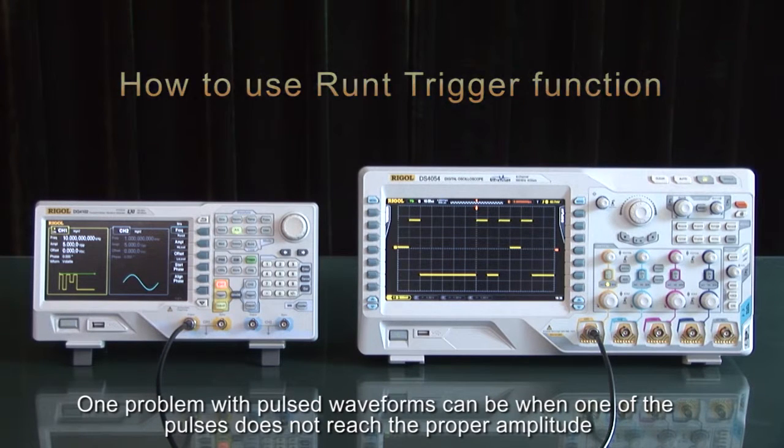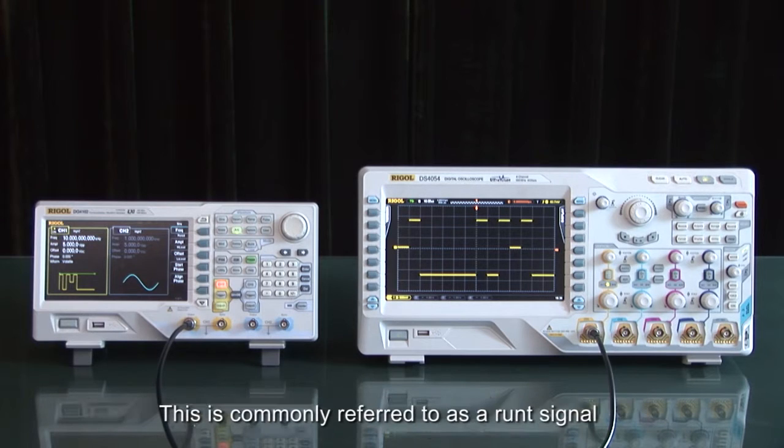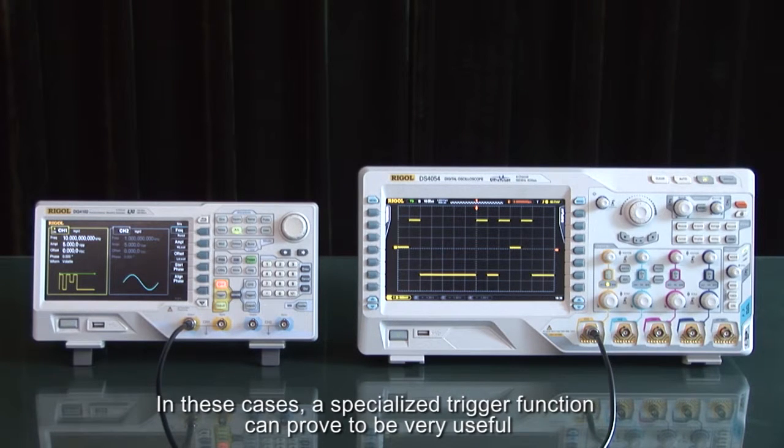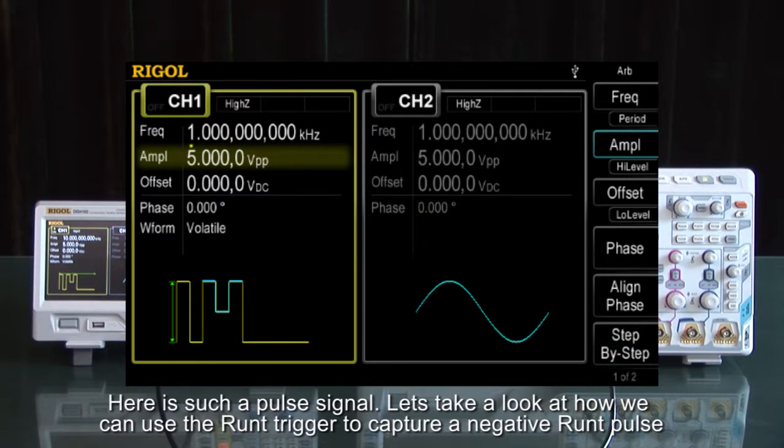One problem with pulsed waveforms can be when one of the pulses does not reach the proper amplitude. This is commonly referred to as a Runt signal. In these cases, a specialized trigger function can prove to be very useful. Here is such a Runt pulse signal. Let's take a look at how we can use the Runt trigger to capture a negative Runt pulse.